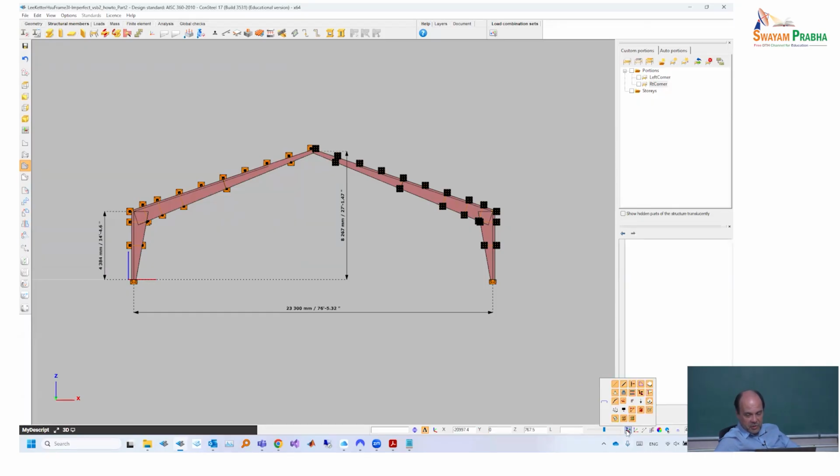It's definitely switched off. So if you come here to the visualization, we already saw during the last 2 days that for many reasons, if you don't see something or you don't want to see it, you can come here, and for each type of object, you can switch off the representation from the screen. This seems to be a nice thing up to the moment when you switch off also those things which are relevant, but you forget that you switched them off. And then you suddenly don't understand your model anymore because it seems that you have no more supports. You start to define a new support set, and then you will suddenly have 2 supports at the same position. And when you start the calculation, Consteel will say, no, you have too many supports. And you say, oh. Okay, so be careful with this game.